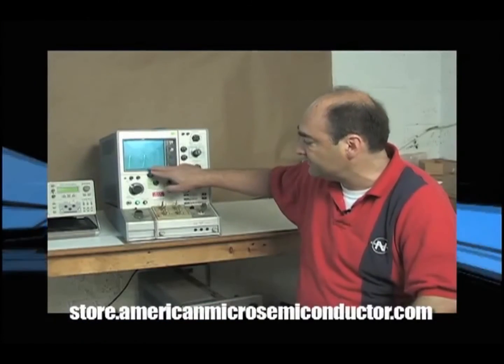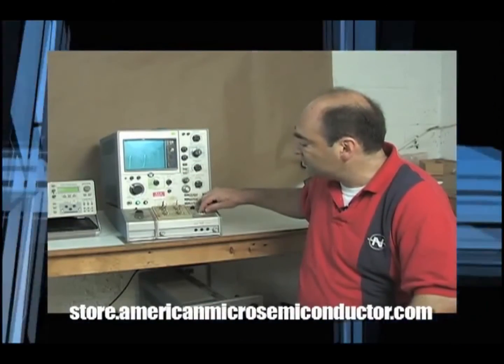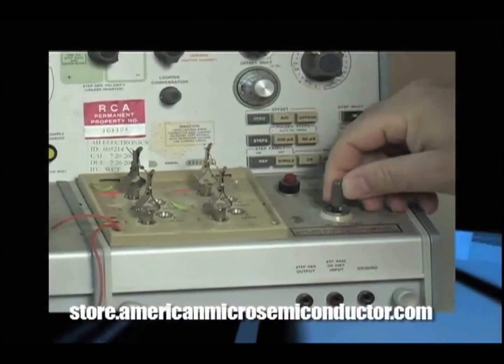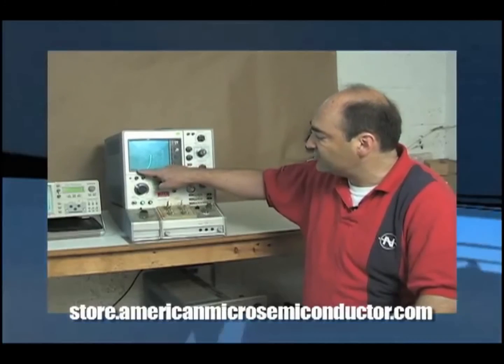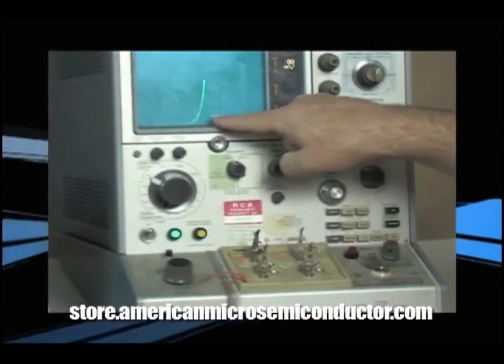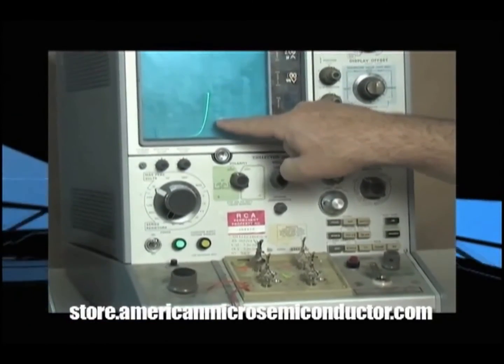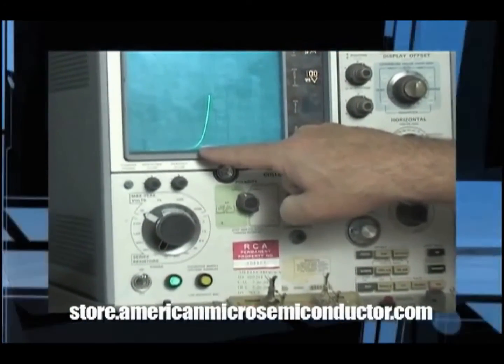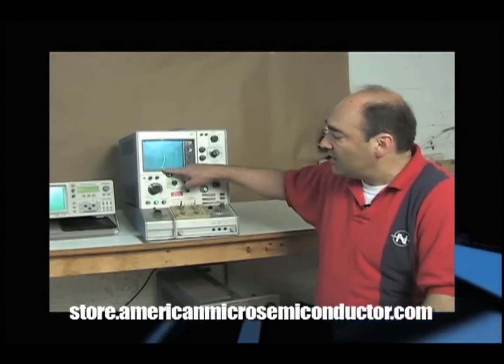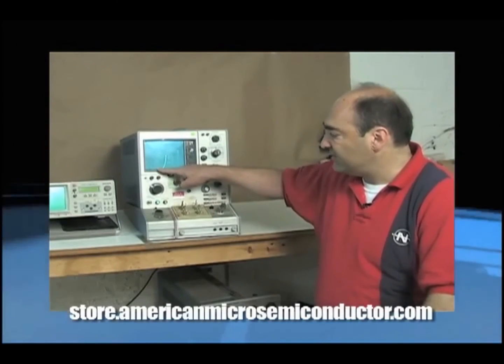So when you're specifying your tunnel diodes, you want to specify the range in which you want the tunneling concept to exist. Now, we'll switch back to the 1N4007, and you'll see that the forward voltage drop is between 5 and 6/10 of a volt in your conventional diode. Now, this is a conventional diode.